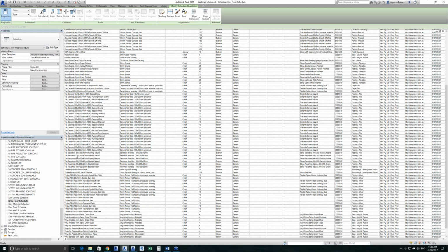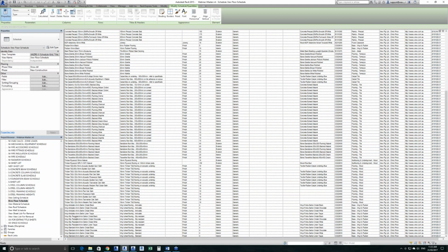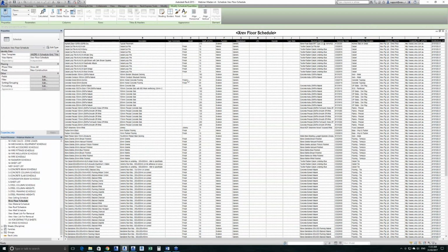You'll see that finishes have a model of finish, so they can very easily be filtered out of your slab set down plans and things like slab set out plans and floor finish plans, so you can differentiate between the two. We have depth information, so that those thicknesses can all be tagged and scheduled as needed. Function data is set correctly, structural materials are set where applicable, and again, assembly codes and all that sort of stuff has been assigned.